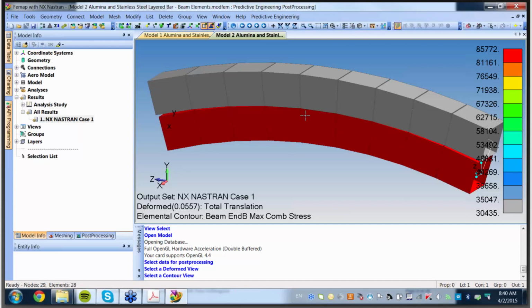That is the reason why you want to do a thermal stress analysis: you have different materials in your structure, and they're going to be heated up. These different materials with different CTEs make a very powerful load set because it just creates huge forces. You have a strain, and the amount of stress depends on the elastic modulus of the material. So thermal stress is one of the most scary, dangerous, intriguing load sets you can get because you can create such high forces on your structure.